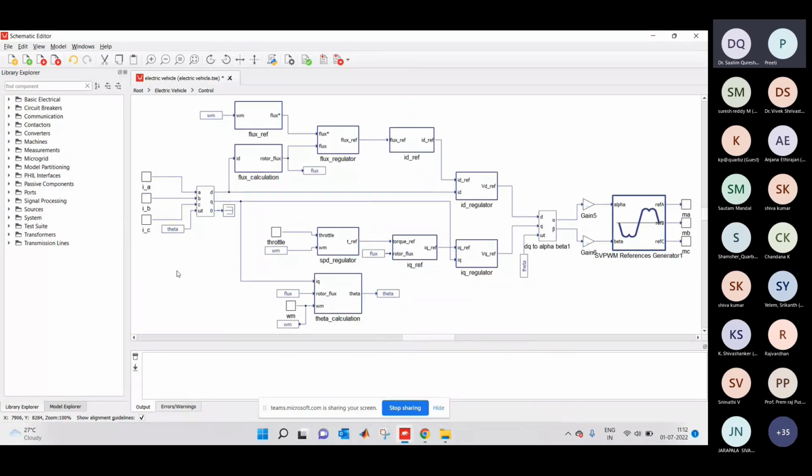This model also includes a 20 kVA load for simulating UPS mode, which is done by switching the battery inverter to grid-forming mode and disconnecting from the grid. Let me tell you one more thing: this Typhoon HIL example model does not implement any specific manufacturer's topology for the drivetrain or the battery converter.